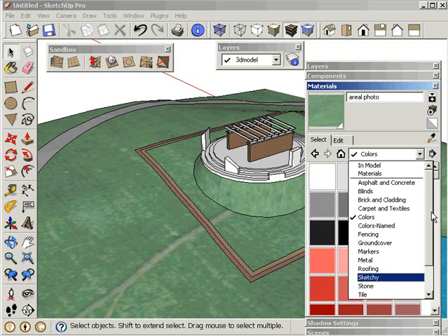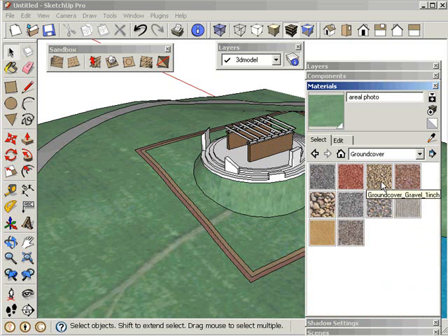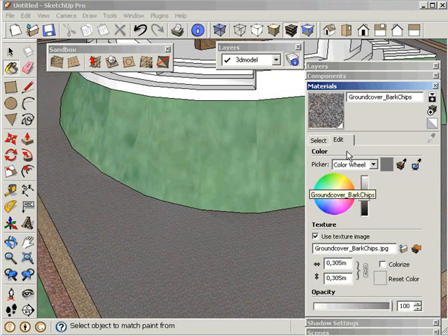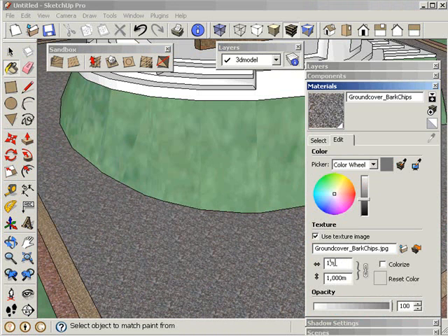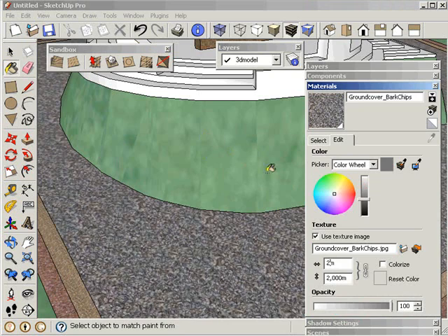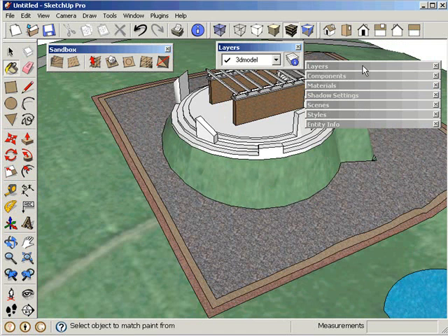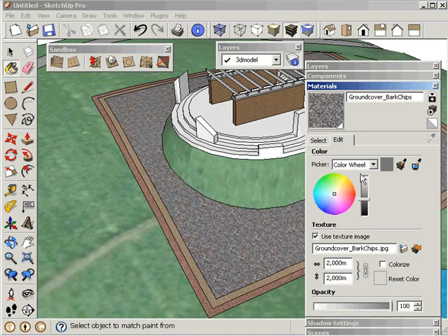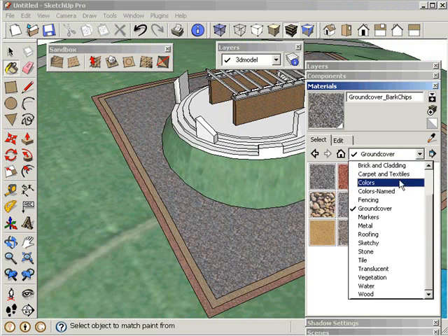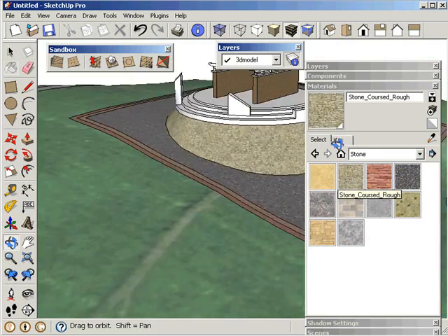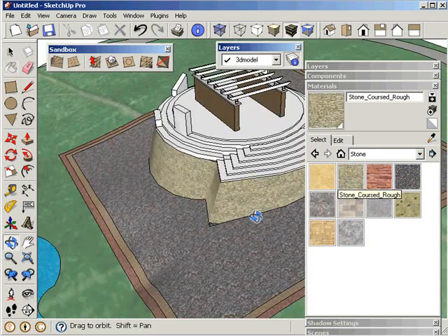and we could go further and bring some textures to the surrounding of this pergola. We find gravel, or maybe something like this. Just edit the scale of the texture, give it the right value, something like this, and then we go and try to find another texture that we give to the stones. Here we give the stones this material. Yeah, that should be okay.